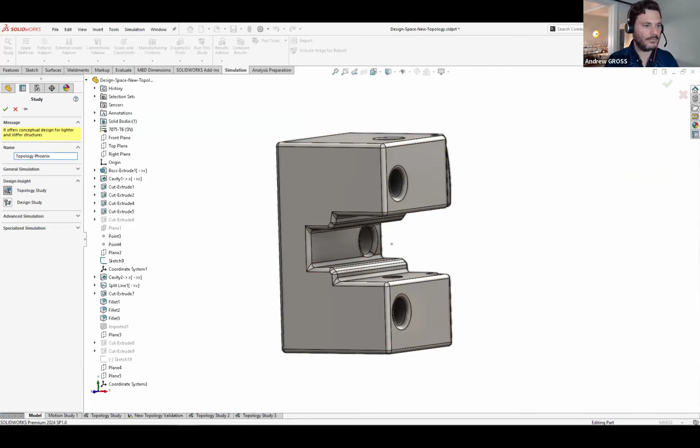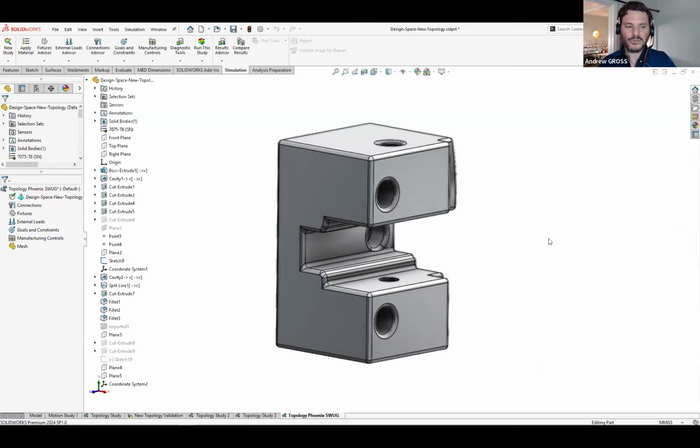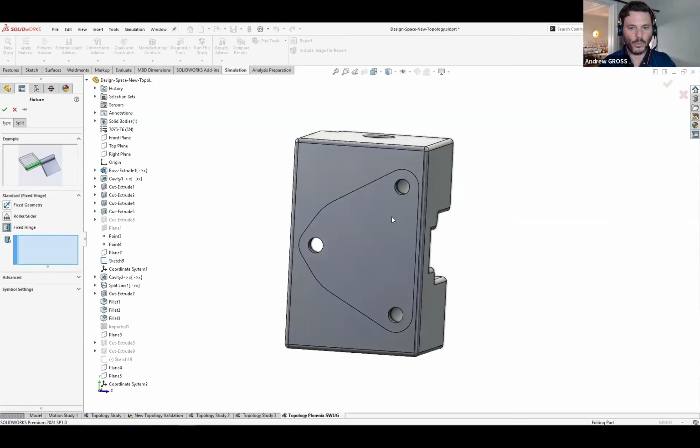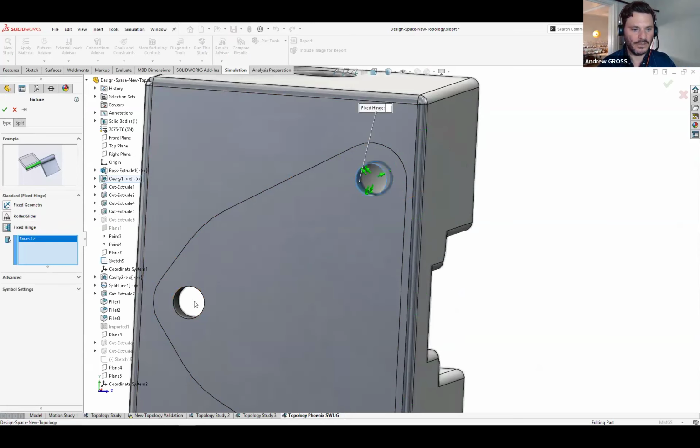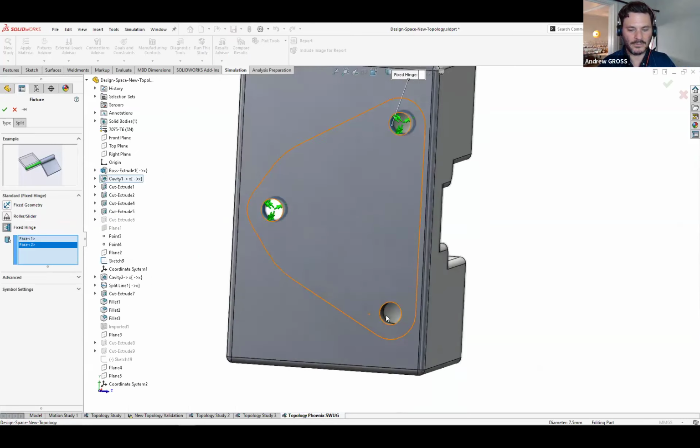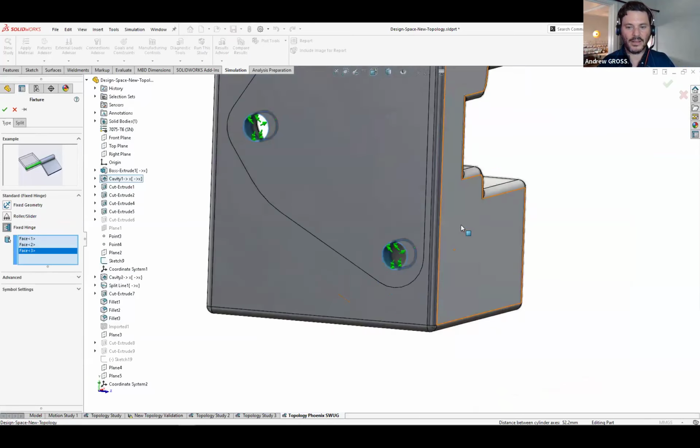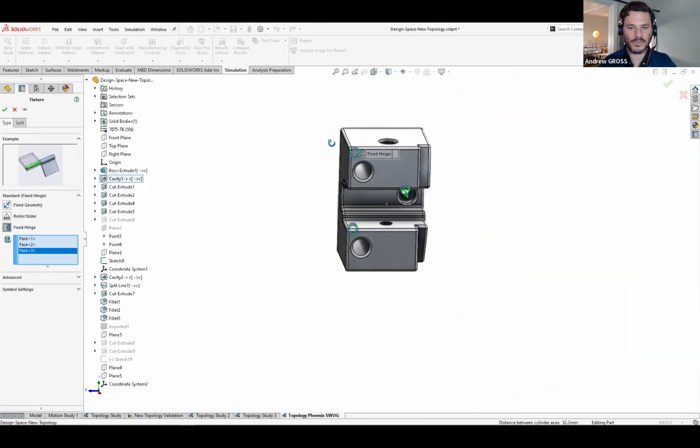So setting it up is similar to creating a finite element analysis or an FEA study, but you'll notice there are some things that are a little different, and then the results are definitely very different. Okay, so we already have a material here. So the first thing we do is add some very simple fixtures, just like we did before. We'll add that fixed hinge where we know this thing's going to have to be bolted to that steering plate, just like we ran that FEA study previously.